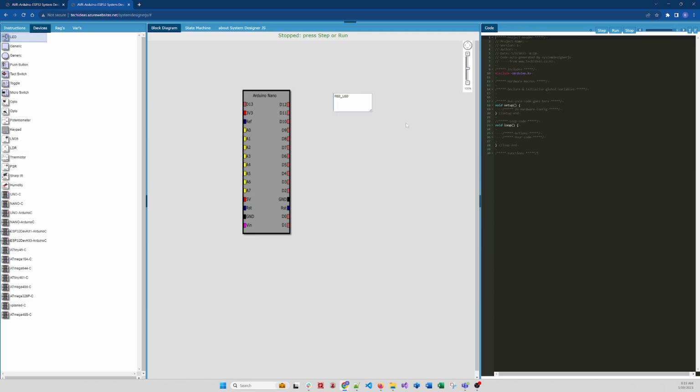Okay, and there we go. And I use capitals for this. Right, so there's a red LED. That's cool. Now I need to connect it to a pin of the microcontroller, and I could connect it to pin 10. Now if you hover over 10 here, you'll see at these inputs and outputs that a little faint square appears, and you can just draw from that to the LED.